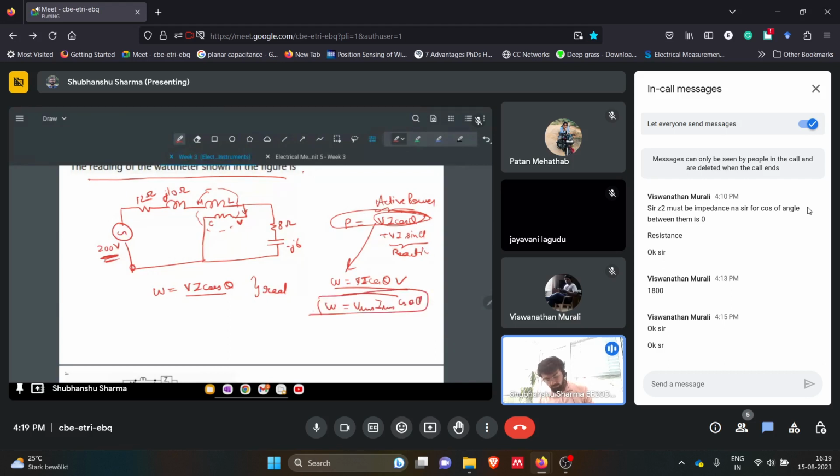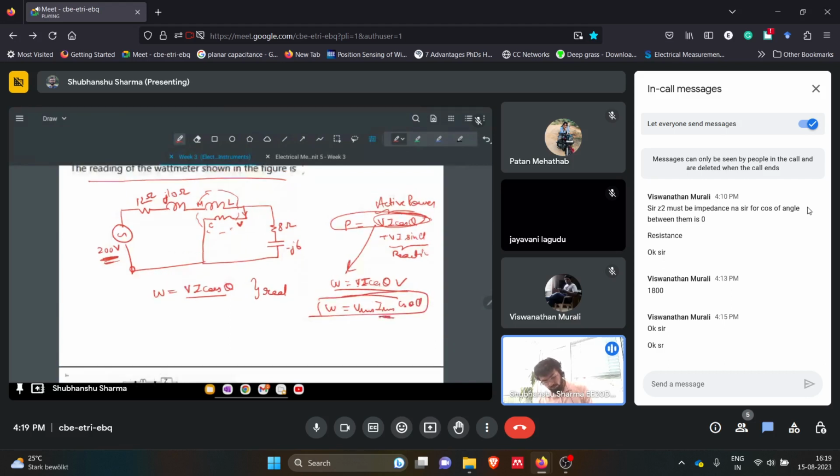So now this will be the voltage across the power coil, this voltage. We will have to calculate this. First we will simply calculate the current of the whole circuit. So what will be the current? IRMS, let's say IRMS. Simple, just don't be afraid if there is an inductor or if there is a capacitance.